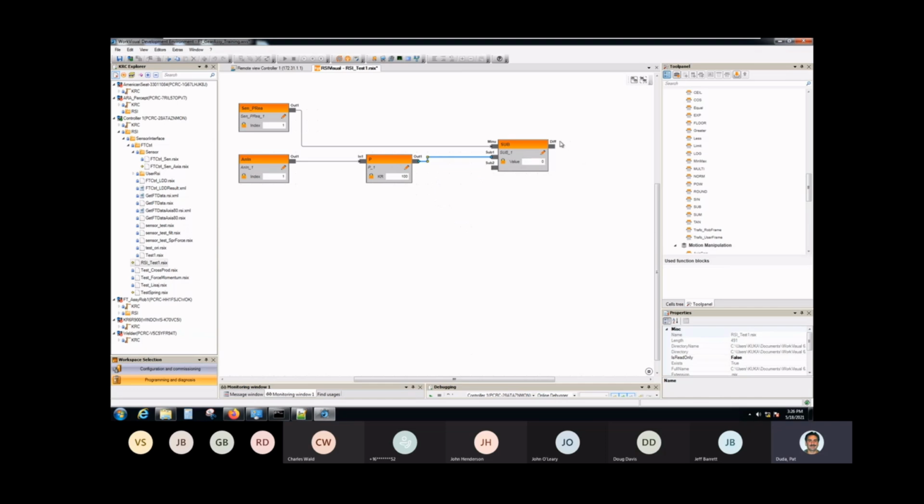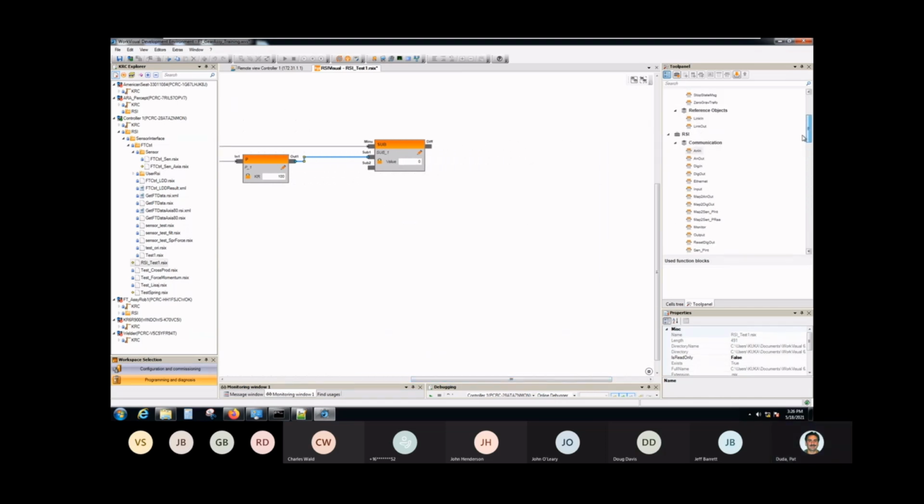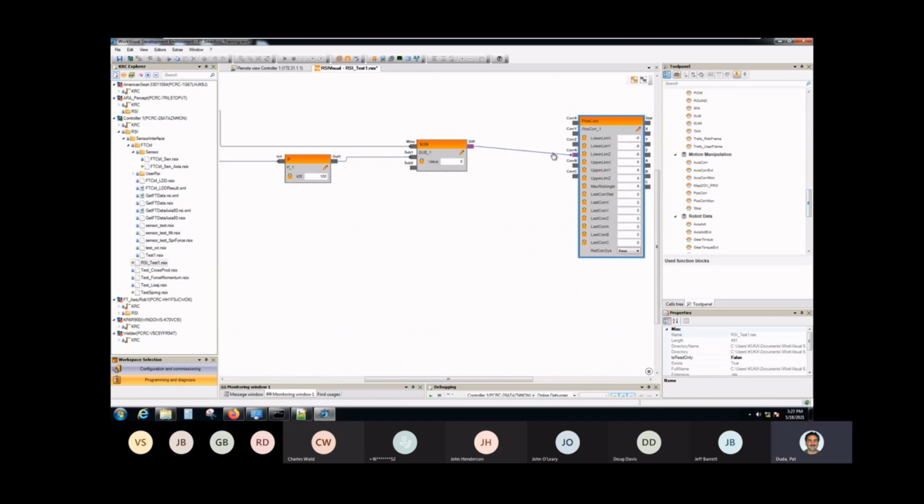Next, we'll add a pose core block, which stands for position correction. This makes the adjustments to the normal planned motion. We can select a drop-down at the bottom to define if the adjustments are in base, tool, or several other coordinates. So we wired our adjustment into the Z. So the adjustments will be in Z of base.